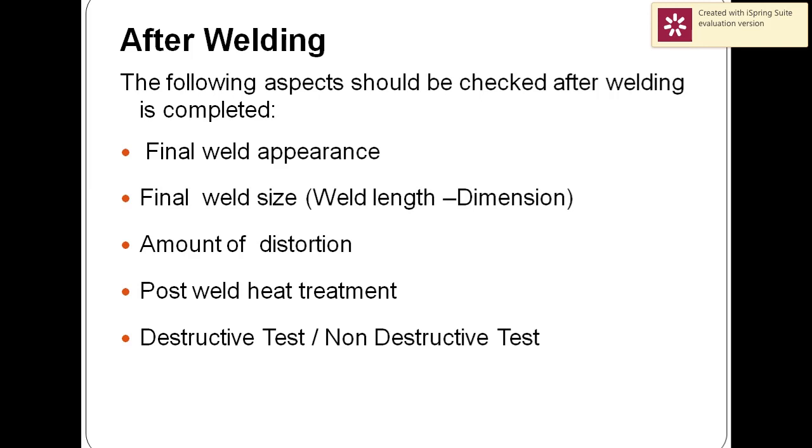Finally, what type of test you have to choose: destructive test or not. If you recruit a new welder, mostly you prefer the destructive test. Sometimes the particular component needs to be reused; at that time you mostly prefer non-destructive testing. So based on the customer requirements, you have to choose it. Thank you.